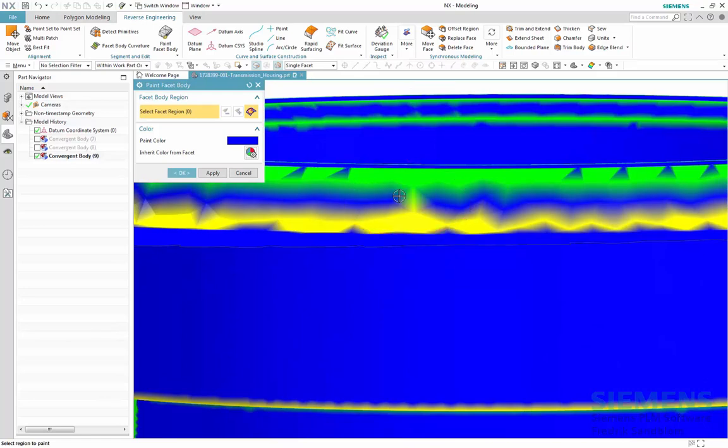However, this might be a bit time-consuming, so we choose an additional option to directly set the color coding so that we get the precise result that we are expecting. In addition to the detect primitive and facet body curvature, you can manually manipulate the color code to better fit your purpose. Simply set or inherit the color that you want to change to and start selecting areas that you want to recolor by setting the appropriate selection rule.